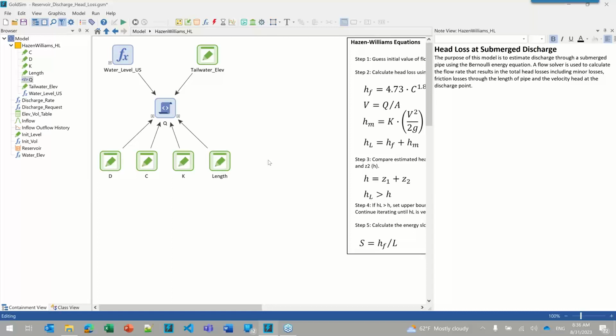head losses. Well, I say they're high head losses because I'm assuming that there's quite a big difference between the upstream water level and the downstream. I'm showing a tailwater level of 35 meters and an upstream of 40 meters. So a 5 meter difference is quite a bit of head loss. So we'd need a pretty high flow. So anyway, I had a choice with the numbers I was using in the other examples. I couldn't reproduce it unless I had a very small difference in tailwater and water surface, and that didn't really seem to make a lot of sense to me.